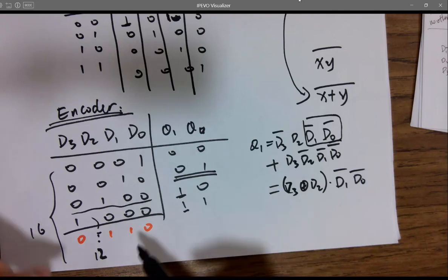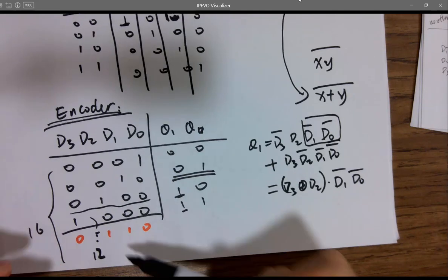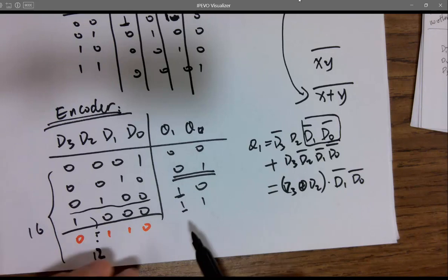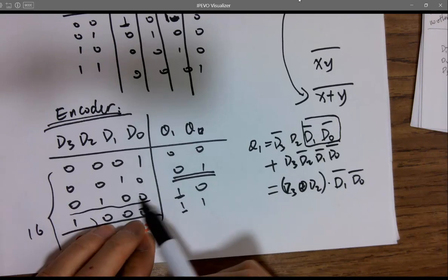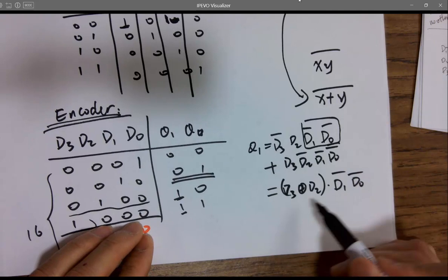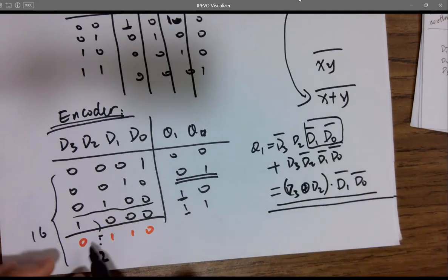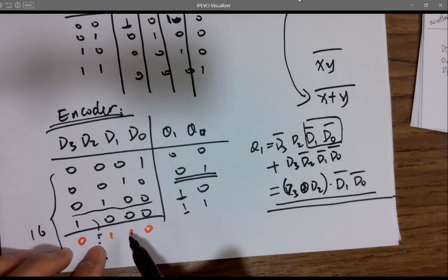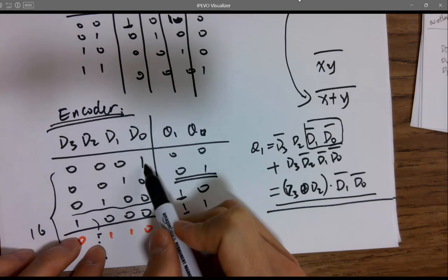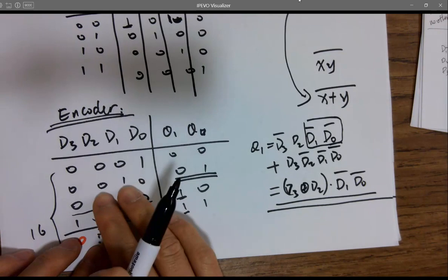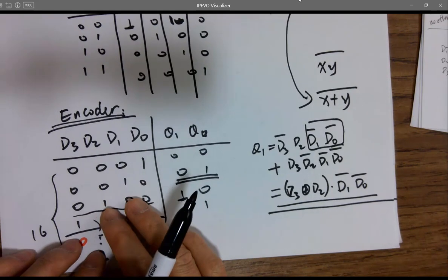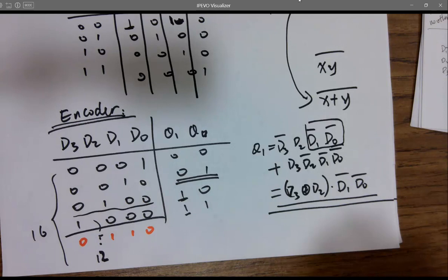But the problem is you don't have all the possibilities listed over here. So I have to consider these two, and I have to include all the things over here, which will cause a problem. For example, the sensors are designed not to be on at the same time, for multiple ones to be on at the same time. But there might be some issues like noise or disturbance of the system and getting one of the bits flipped, right?